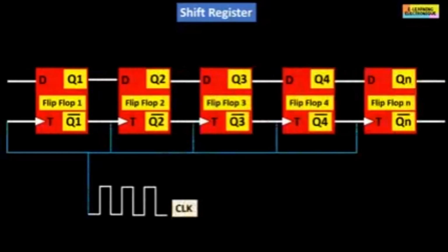The configuration of the shift register is done according to this diagram. Several flip-flops are connected in series. The output of each flip-flop is connected to the input of the next flip-flop. The information or data enters serially into the first flip-flop and leaves serially from the last register. The output of each flip-flop enters the next flip-flop, but the information also takes a second path which is parallel to the outputs of the other registers.